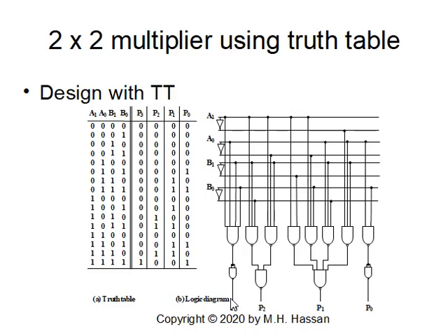So we got easy implementation, fast parallel circuit, no feedback, okay, and slightly complicated because it uses many NAND gates, and we have 4-input NAND gate here, 2-input NAND gate, and 4-input NAND gate, many actually multi-input NAND gates we use, but the outcome is very good, a fast multiplier.